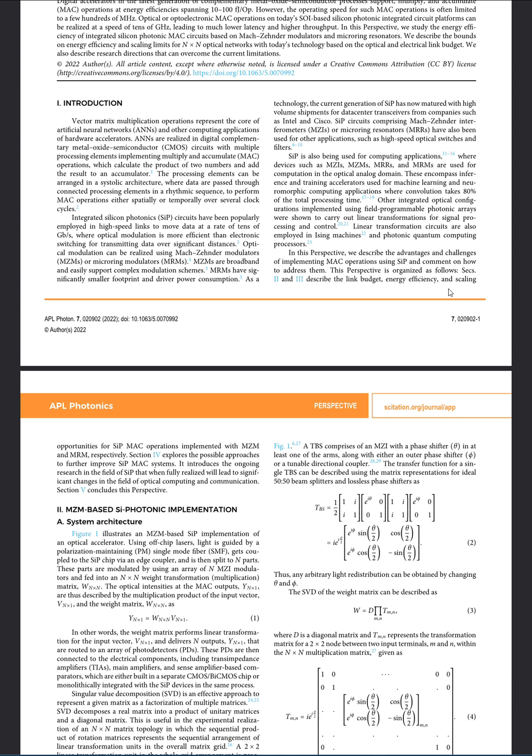And silicon photonics can be used in computation in the analog domain, through utilization of these Mach-Zehnder interferometers, micro-ring resonators, and modulators. These can be used for training accelerators in applications where convolution takes 80% of the total processing time, such as machine learning and neuromorphic computing applications.